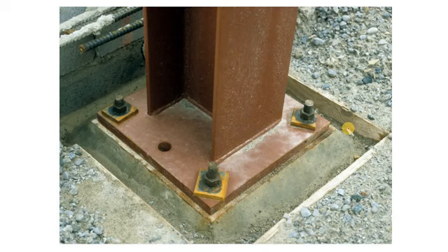Well, pause the video and try to visualize the load transfer. Yes, the column web transfers the shear to the plate through this welded connection, and also if there is any moment acting in this column, it is converted into a push and a pull like this. As the flanges are connected to the plate through this weld, this push and pull are also transferred to the plate.